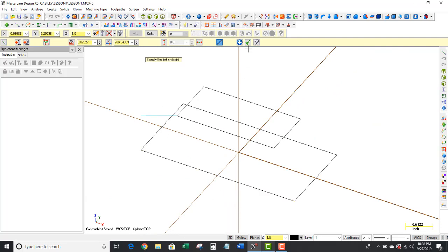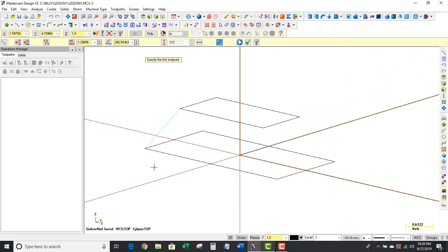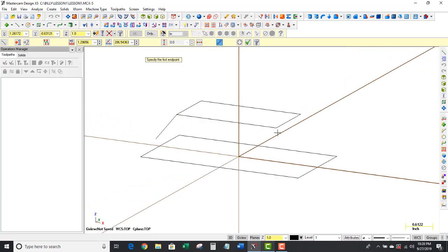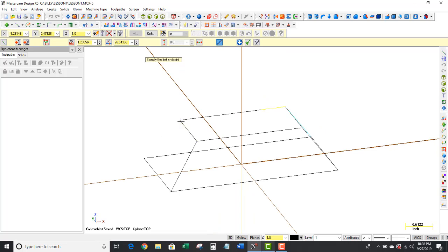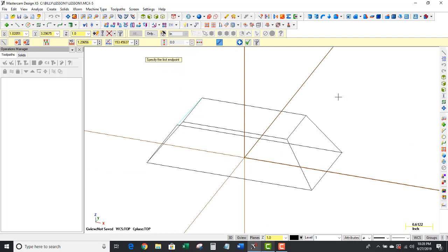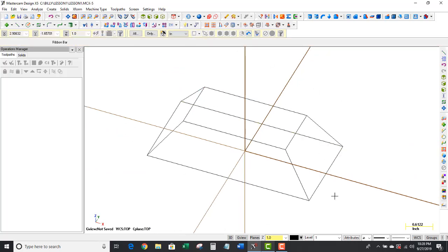Okay, so again, if I undo that and then switch to 3D, now when I select line and I let it snap to this corner and to that corner on the rectangle below, it will now let me connect because now I'm set to 3D. So now it will draw wherever my mouse clicks or snaps to existing geometry. Alright? And then we click OK.